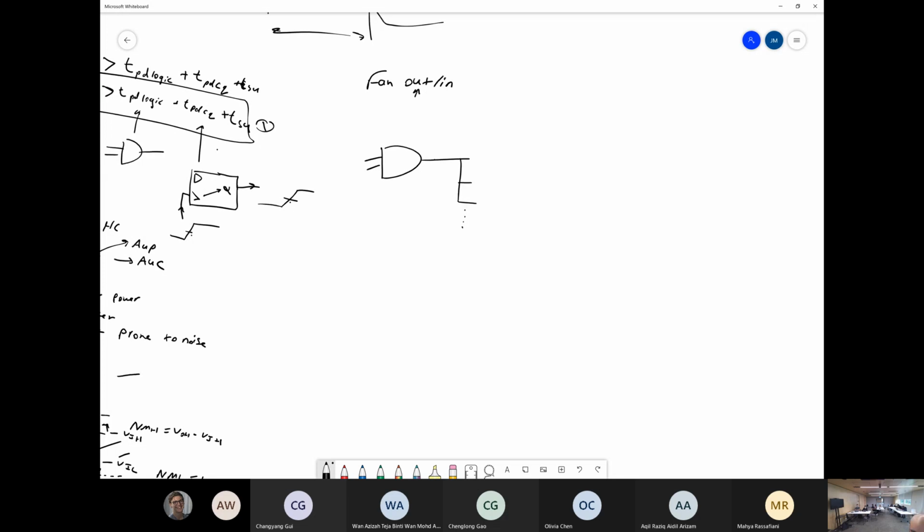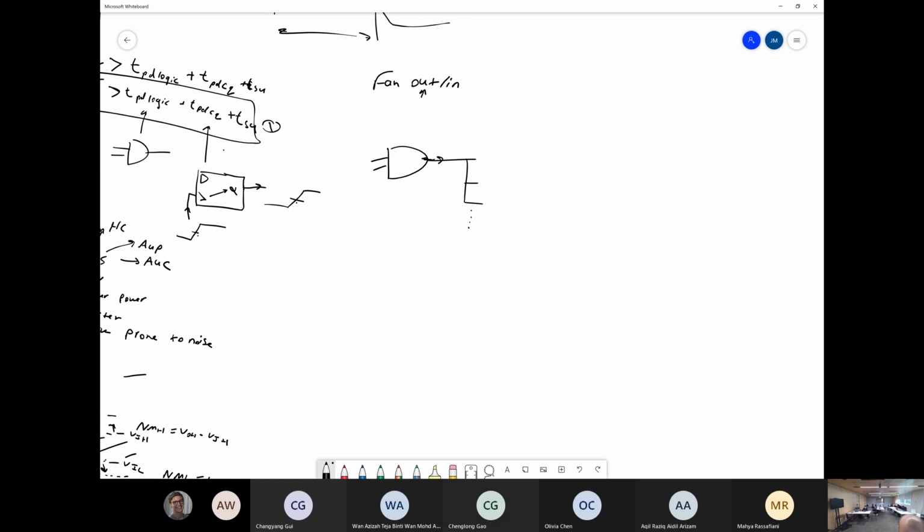So basically, say for example, if my maximum current for a high value is say 20 milliamps flowing out, right? And I have just a whole bunch of inverters, keeping it simple. Each inverter draws a milliamp when the input is high. This drives 20 milliamps when the output is high, this sucks in 1 milliamp when the input is high. How many inverters can I have attached? 20. It's that simple.